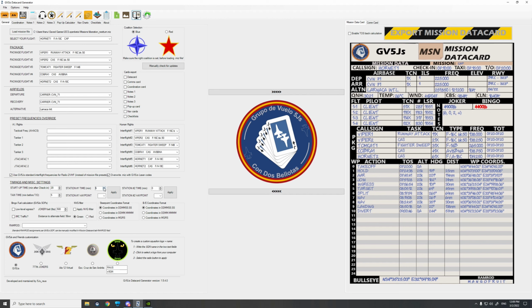And when we hit apply, this will add 10 minutes to the time over steer point of each waypoint after waypoint 2, meaning that the join waypoint, which was planned at 7:51, will now get shifted to 1 minute past 8, and subsequently. So I hit apply and there it is. We have still a second station time that we could use for a second air-to-air refueling or a second holding pattern, whatever we want to.